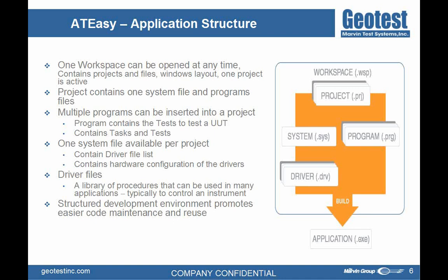The driver module is where you have reusable libraries of code. Typically the driver is code for communicating with an instrument or with various instruments, but can also be apart from instruments. For example, the test executive is a driver that is not targeted to a specific instrument. It's a library of routines that can basically look at your ATEasy application, create a user interface unique for that application, and then provide that user interface to the operator.